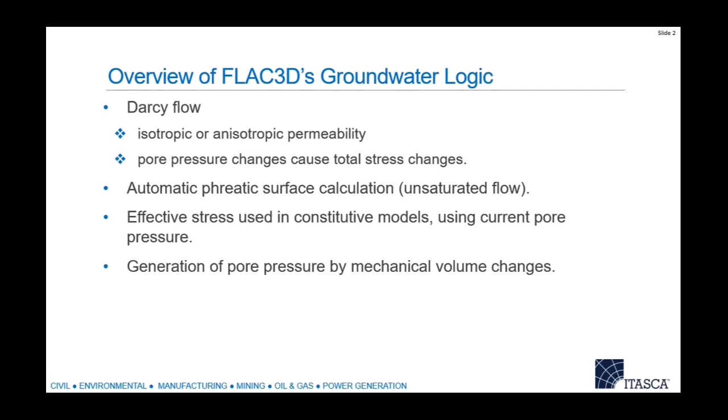Okay. And we do two-way coupling. So we alter the effective stress for the constitutive model. We alter the stress the constitutive model sees. But we also, when the mechanical logic generates volume changes, it will automatically generate pore pressure in the fluid. That is also the default setting in the current version of the code. In the updated version, those will not be the defaults. You'll have to turn them on to make it more complicated. But right now, we start off with kind of everything present. All right.